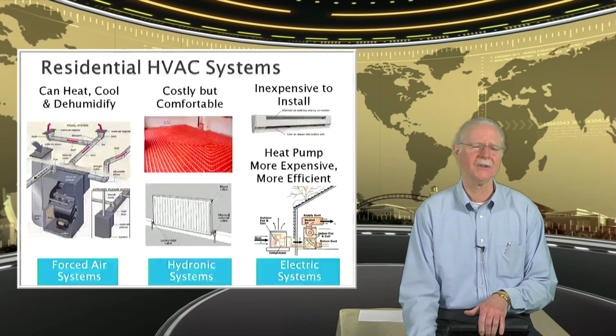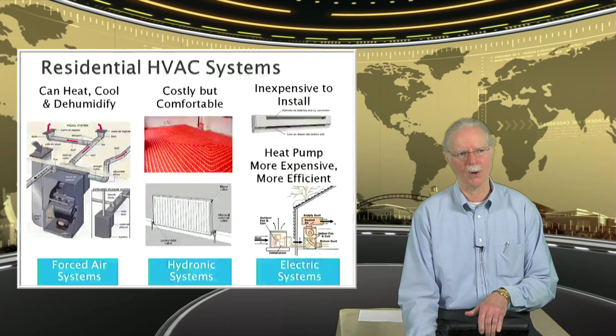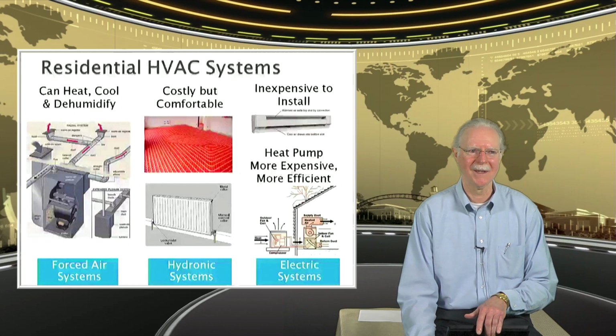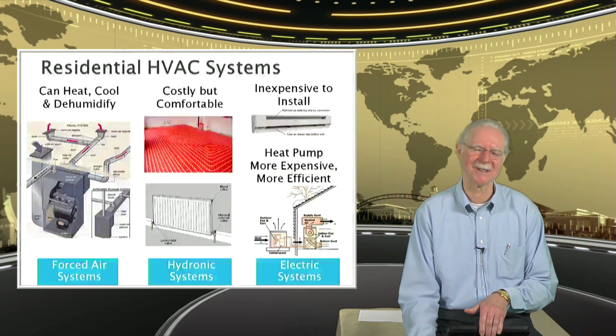The second place you can run into inefficiencies, and the reason why blanket comparisons don't work, is that in a lot of cases, these are done on buildings that are on a slab on grade, and often a lot of the heat energy is lost to the ground because the floor slab and the ground aren't isolated appropriately. So this blanket statement that this is a better way to go is never a good choice. But it does have the potential, especially if you compare it to a forced air system where all the ductwork is in the attic and uninsulated. Now you've killed the efficiency of the forced air system.